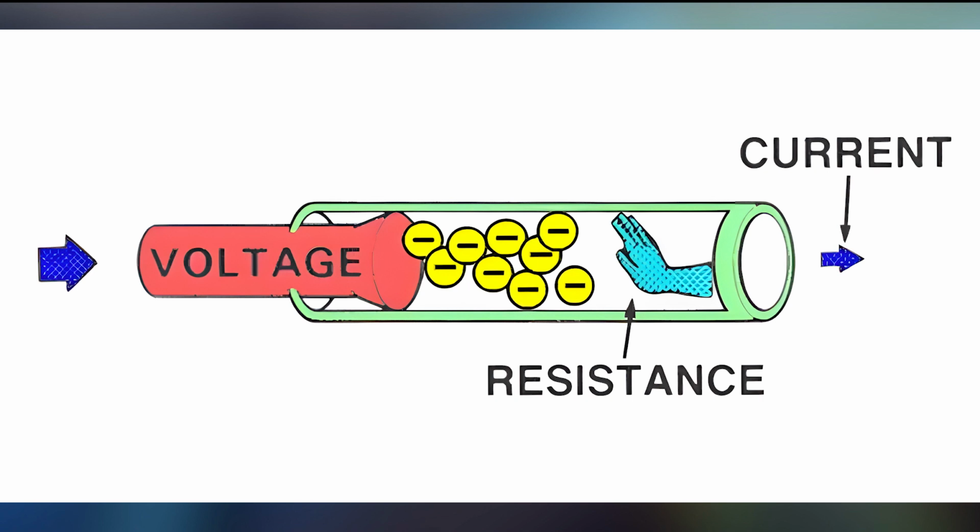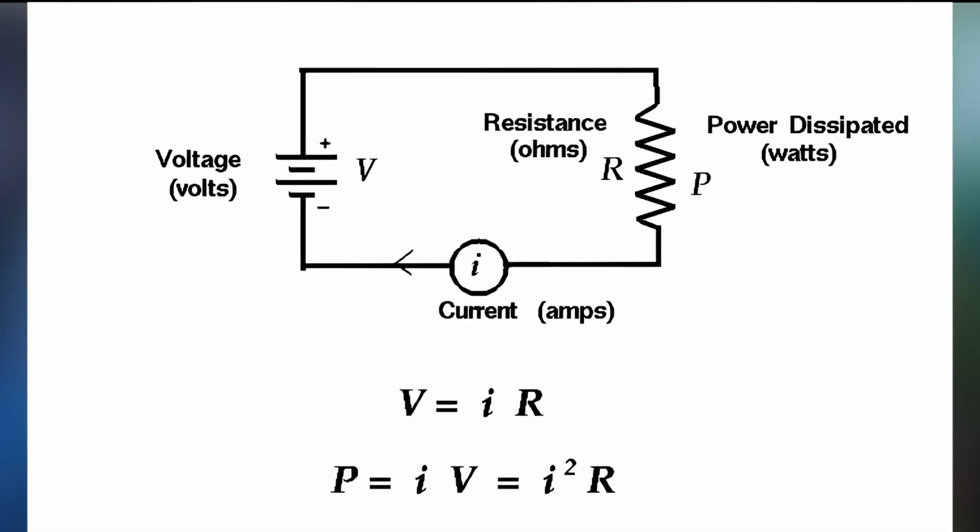Similarly, if you have a certain voltage and push electrons through a conductor, the more resistance you have, the less current you get. And so there's this famous law in electrical engineering known as Ohm's law. That's spelled O-H-M, if you haven't seen this before. Ohm's law states that for linear resistors, not everything obeys this law, but for the moment we'll just pretend that everything obeys Ohm's law for simplicity. For things that obey Ohm's law, there's a direct linear relationship between current and voltage. So the algebraic version of the law is V, voltage, equals I, current, times R, resistance.